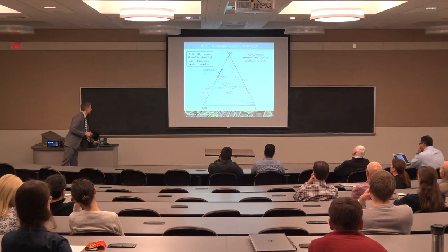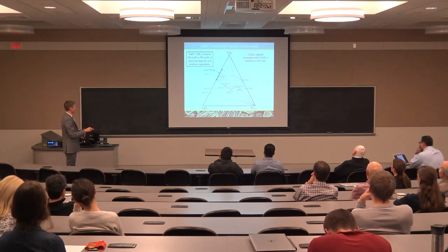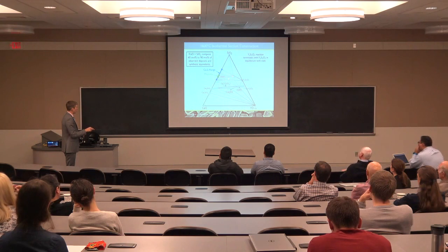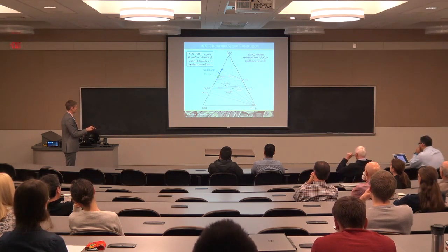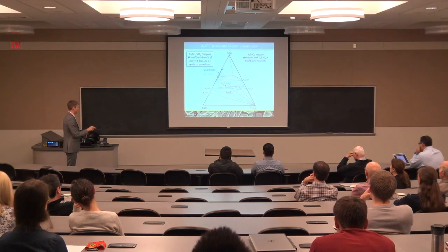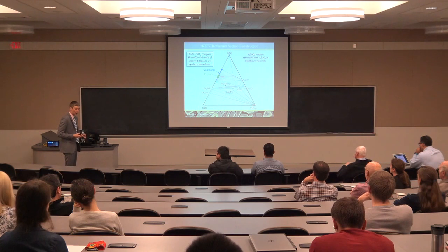And if we think about dissolving an yttrium silicate coating, this is one of the materials used for these environmental barrier coatings. We find that initially we might form some apatite, but eventually we'll get to a point that we have the coating materials in equilibrium with the liquid. And once that happens, we would expect that the coating degradation or dissolution would stop.